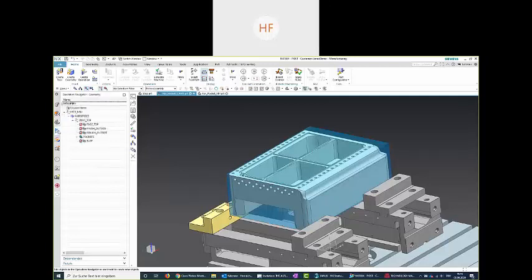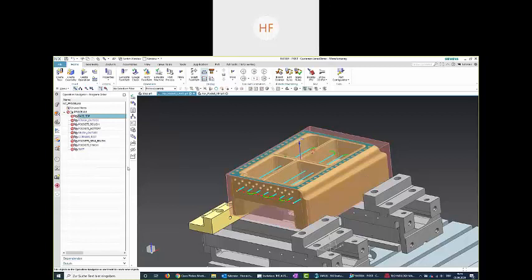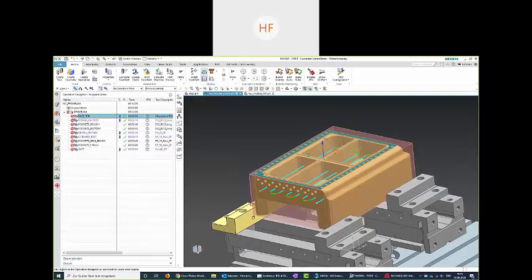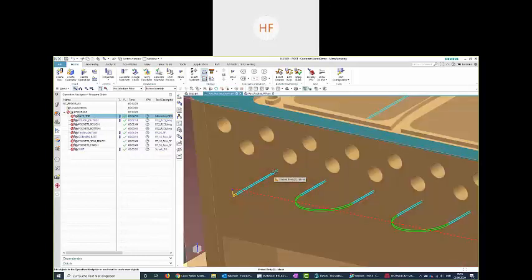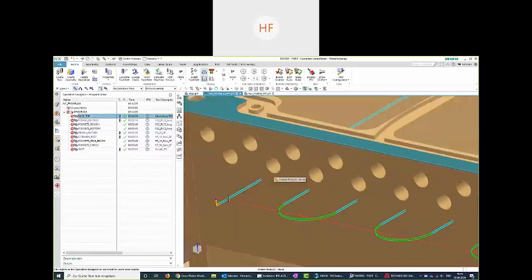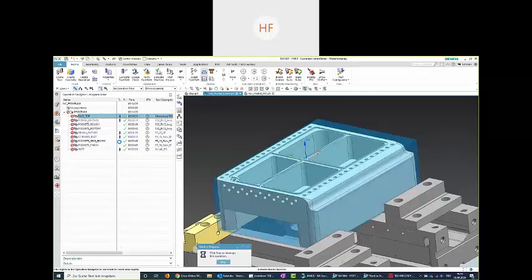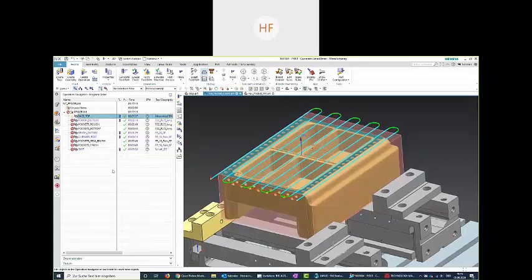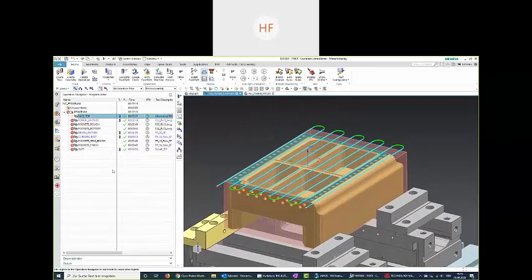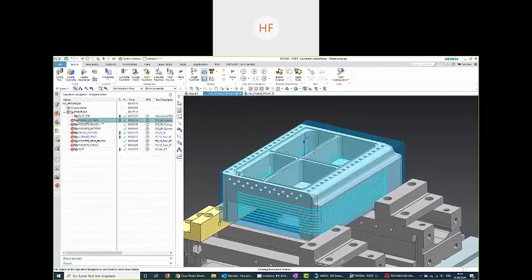When I take a look at my operation navigator, I see that my previous operations, for instance the face top operation, is now outdated. I have to update it first. By clicking on it once, I also see my old outdated tool paths. They were going right through the part. That's not correct in this case. By making a right click on it and generate, we will see that the operation, for instance face top in here, is being updated automatically. I don't have to do anything at all.